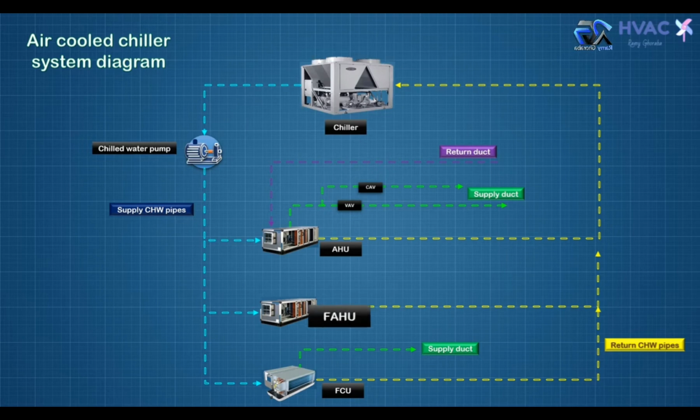Now we'll talk about fresh AHUs. These fresh AHUs receive fresh air coming from outside through a fresh duct, and we should install a centrifugal blower to avoid any sand getting inside the duct. We should install a volume damper to control the quantity of air we take from outside, and a pre-filter to make sure that there is nothing harmful in our air.